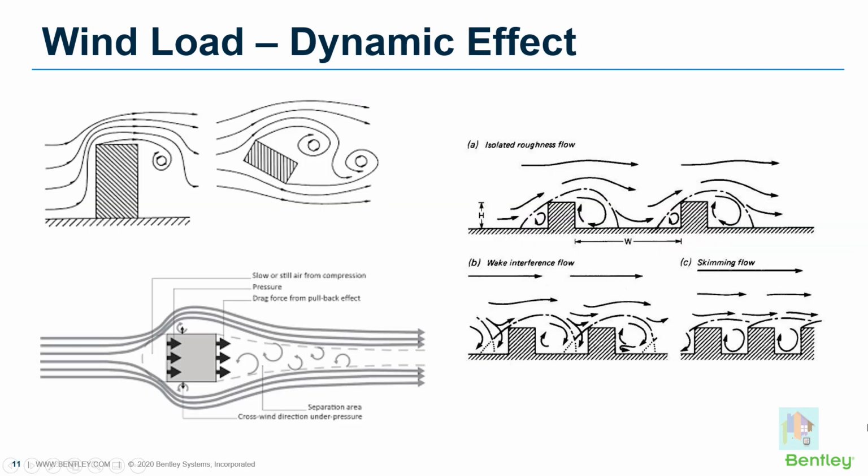In general, we consider wind load as a static load applied on the cladding or directly on the members and does not compute the dynamic effect. But for any tall structure, it is very much required to include the dynamic effect of wind along with the vortex shedding effect. When wind force is applied on the structure from a direction, along with the direct pressure load on projected area, we need to consider the cross wind effects and drag forces in other parts of the building.